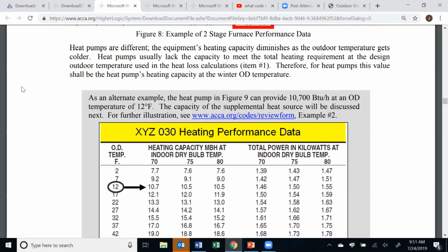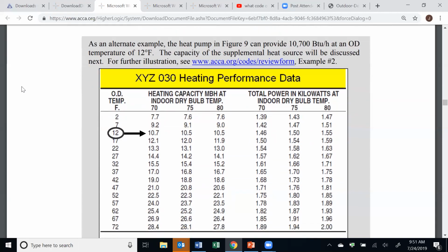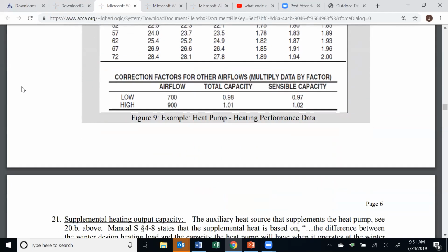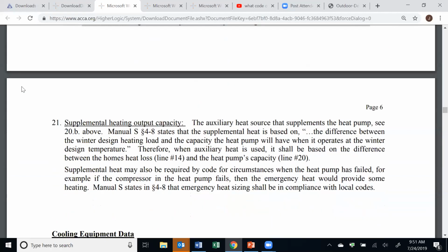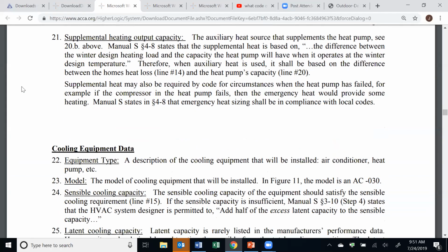Right. No, I'm talking about the furnace. The furnace, oh, okay. If a furnace is running and that heat pump tries to run too, now I've got that preheated air. Typically, the furnace heat exchanger is before the refrigeration circuit coil, the indoor coil. And so if I get that superheated air going across that coil, that's going to wreak havoc on my compressor. Gotcha. Okay. Yeah, you can tell I've never been an HVAC contractor. Yeah, I'm sorry if that wasn't clear at the beginning. Yeah, heat pumps and strip heat are made to work together. That's a match made in heaven.